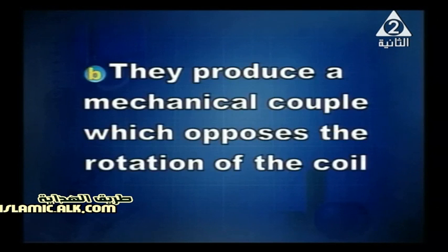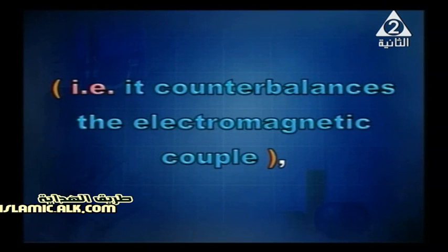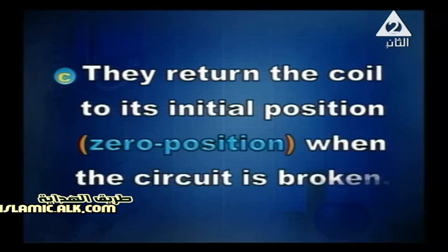They produce a mechanical couple which opposes the rotation of the coil, counterbalancing the electromagnetic couple. Also, hair springs return the coil to its initial, zero position when the circuit is broken.